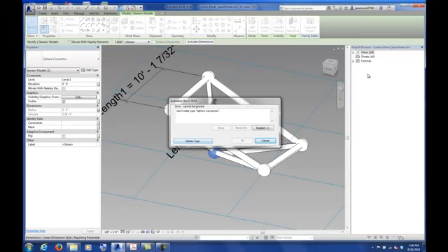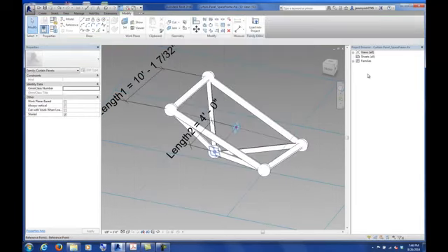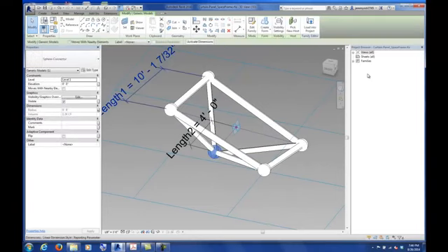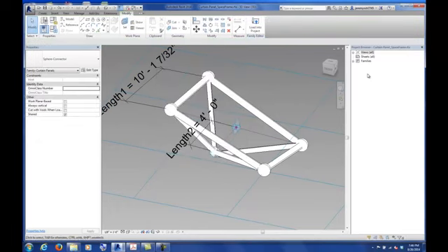Can't make, oh, because it's already set to 0. Give sphere radius B something. So I'll do 6 inches for now. And then I can switch it. The reason I'm doing B, or that one differently, is if you look at your space frame, your perimeters are a lot bigger in the pipe radius dimension than these interstitial ones that go down to that space frame depth.